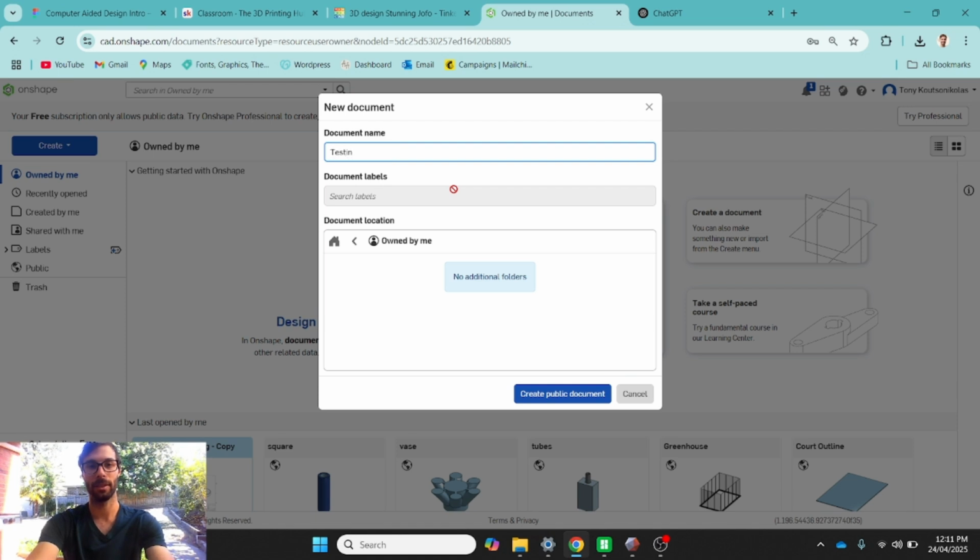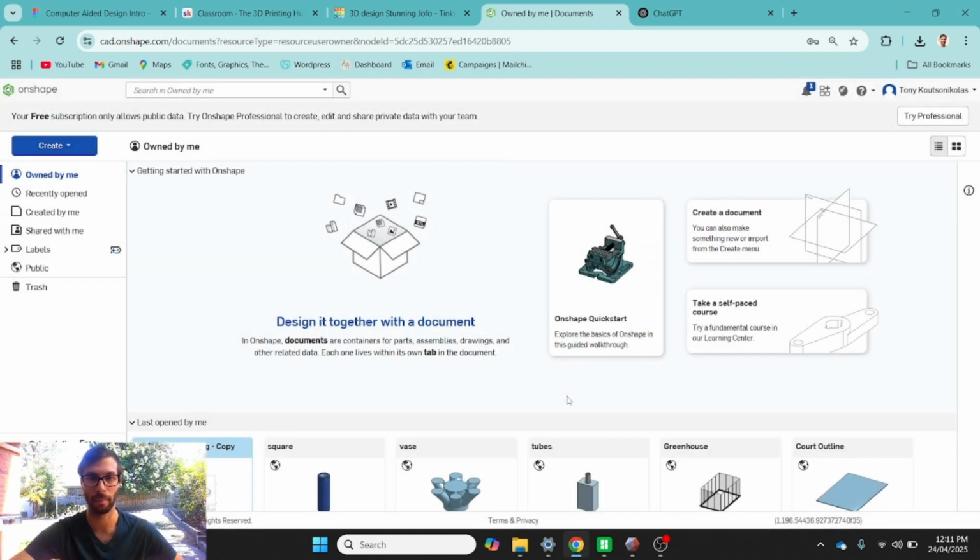And we're going to go for test piece. We're going to make a jig. So jigs are a really useful 3D printed tool, because you could, say, for example, if you wanted to hold a piece and have the marked out regions where you wanted to make some modifications, like you're going to drill holes. You could 3D print a piece to hold it that has holes that you drill through. So instead of measuring each piece and then putting a mark and then drilling into that part, if you had 100 pieces to do, you could have a jig that you just put the part in, and then it automatically shows you what you need to do to it. So jigs are really useful. So we're going to make one.